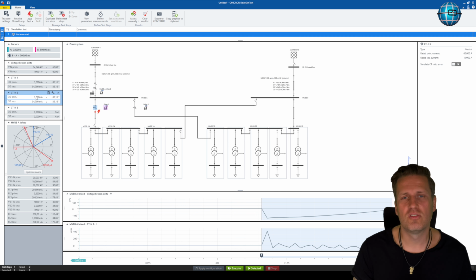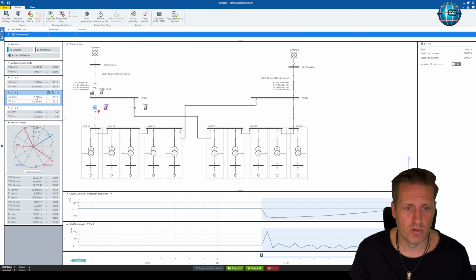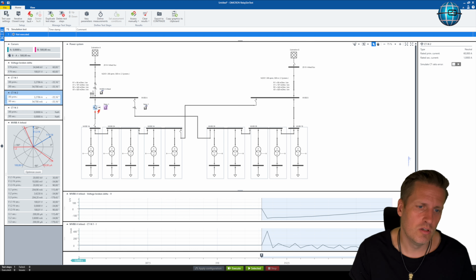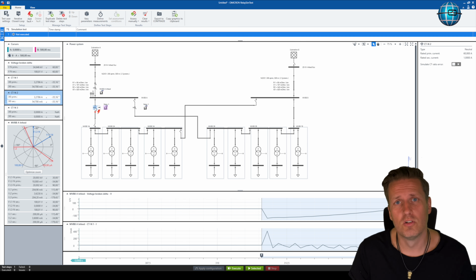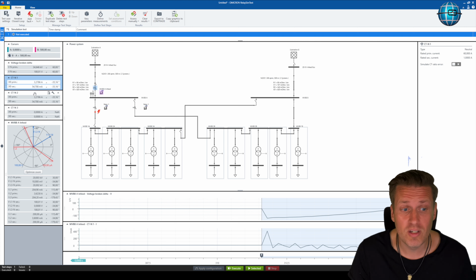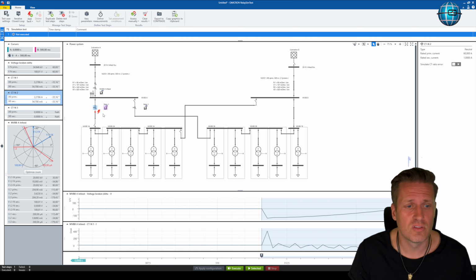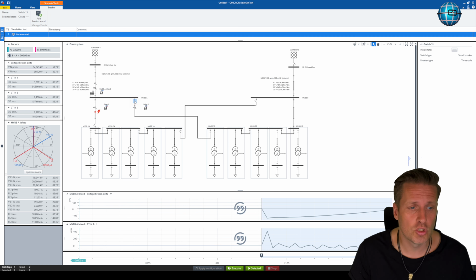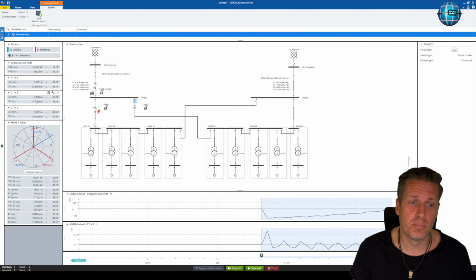I told you everything what's behind the measurement point, so everything what's behind here in this area doesn't affect it. But now we want to see what happens if something will be added which is before this measurement point, and we are connected here before this measurement point. So to cut a long story short, we will get a significant increase of this value. Not this one remains the same, but this one here will increase extremely. Let's have a look. We just close the switch and see it went up to 9.5 already, 9.5 amps. That's a big jump that we just did.